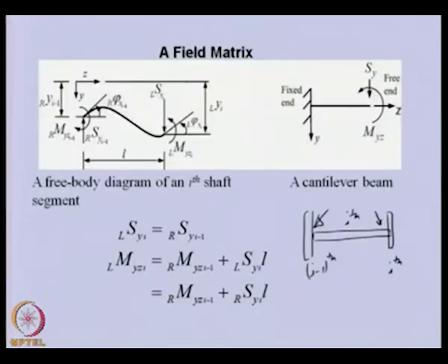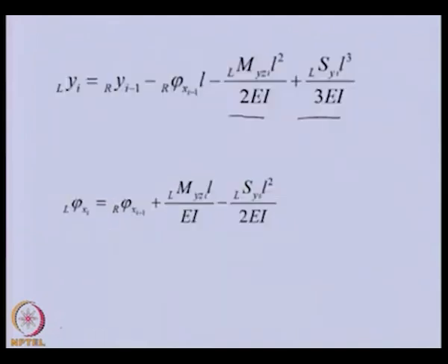again we need to refer to the figure for the slope. Whatever the slope of this end we are giving, in this particular case we can see that if this is the shaft which is rigid, and this is the slope of the shaft which is right of I minus 1, then because of this angular displacement which we are giving to this end, what is the linear displacement of this? This will be slope into length of the shaft. This is the same thing we have done here, and because it is going toward the negative y direction, this negative sign is there.